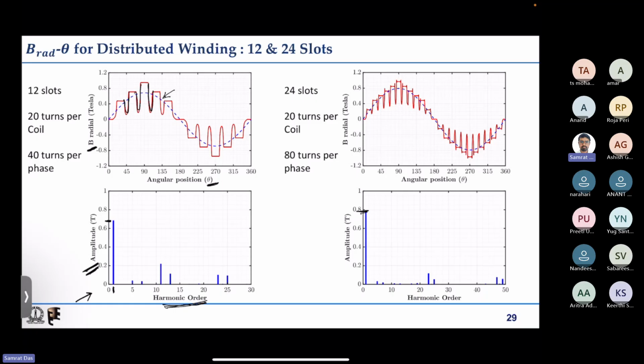So that is why mostly when we study AC machines, the discussion starts with distributed winding, but it does not mean that the rotating magnetic field can be produced only by distributed winding. It is possible to produce a rotating field by concentrated winding, which is very similar to the stator field winding in a DC machine. So that is why I have started from the DC machine field and slowly modified it to realize the rotating magnetic field.